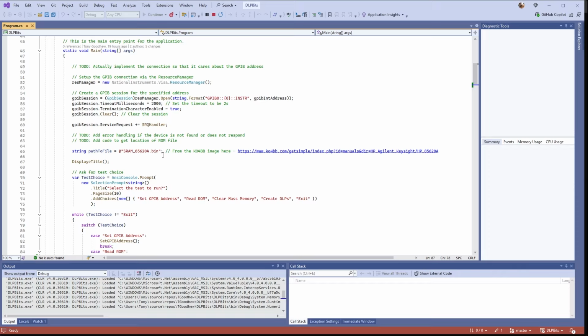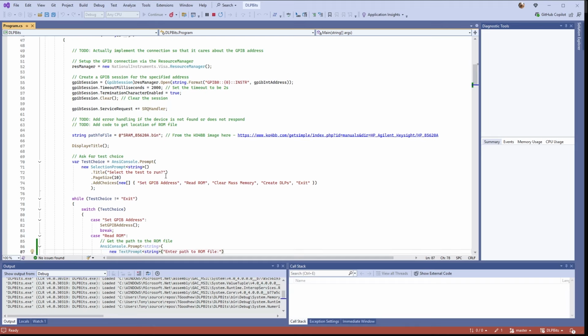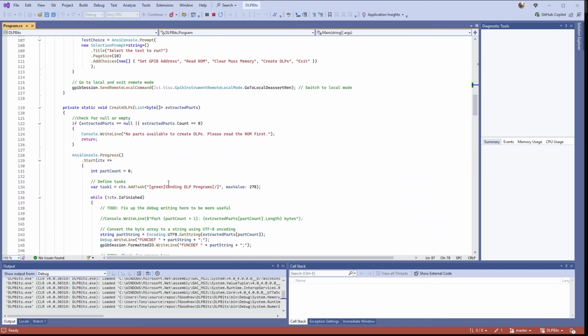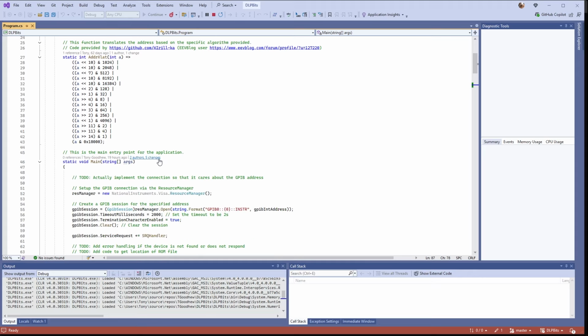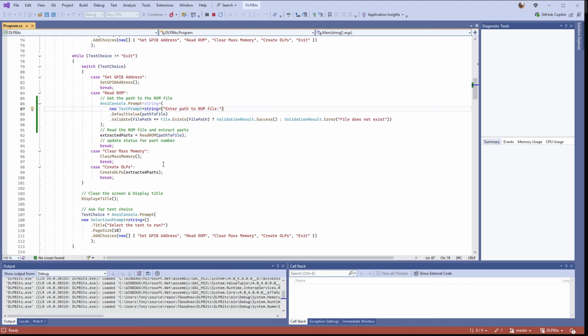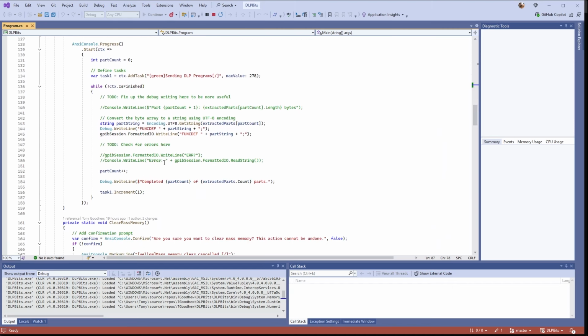So what I can do is go into the mass memory module and extract the stored functions and then reprogram the system. Now, to do that, you had to decode the actual memory setup, because it's just a straight read all the way through. So a great user on the EV blog, Kirill Carr, went and did that work to decode the address lines and how they actually map to a normal straight single memory page.